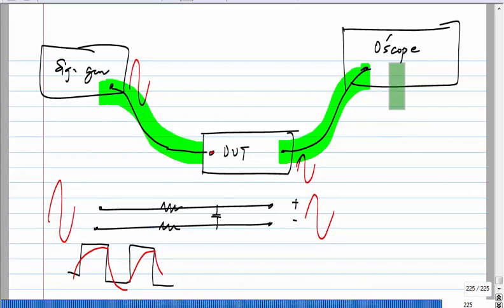This doesn't mean that you don't use other signals for characterizing. Sometimes you may be explicitly required to characterize a system with a pulse and so on. But the arrangements that you need to make are a lot more stringent. That is, you have to make sure that you use the right wire that doesn't attenuate the pulse, which of course will have all harmonics up to infinity. There is no real system that will support all those harmonics, but at least you should have enough harmonics so that the square pulse looks like a square pulse and so on. So it is simply a lot easier to do things with a sinusoid than with any other signal. So that's why they are most widely used. Again, you use all kinds of other signals, but this is the most basic one.